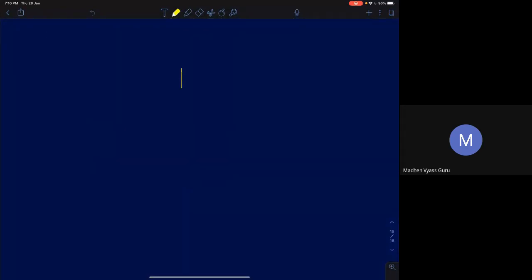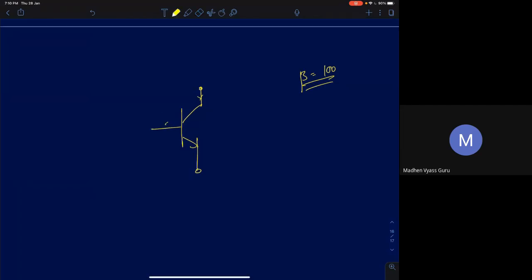Okay, what they used to do is that, let's say you take a single BJT. If I use a single BJT, let's say IB is the base current. What is the collector current in terms of base current? It will be beta times the base current, right? Sometimes what happens is in ICs, you get a beta less than 100. In fact, you will get a beta of 20. What if you want a higher beta? If you want a higher beta, we do what we call a Darlington configuration, named after the scientist who invented it. What we do is something like this.